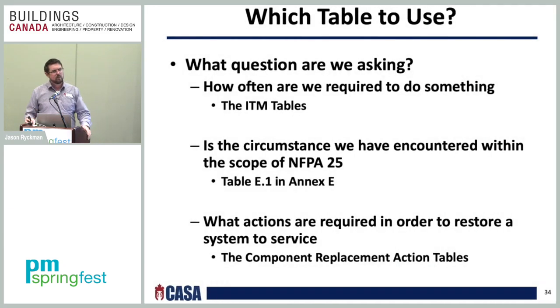Another thing that's good whenever you use the tables is making sure that you use the proper table for the specific question that you have. So you've got to ask yourself, what questions are we asking? If you're asking how often are we required to do something, you look in the inspection, testing, and maintenance tables.